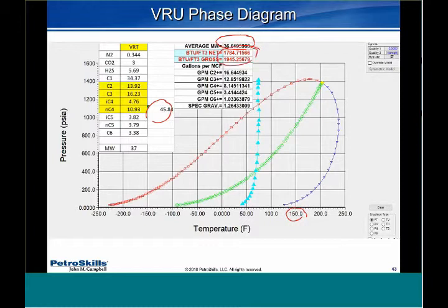It's very high. The gallons per 1,000 cubic feet, if you could recover 100% of the molecules, it's very, very rich gas. In fact, it's so rich that this green quality line is 50% liquid. So once you hit the temperature and pressure and cross that line going from the right to the left, half the liquid's going to condense. So this particular set of molecules is prone to infinite recycling, and this is what you're seeing in your vapor recovery compressors.